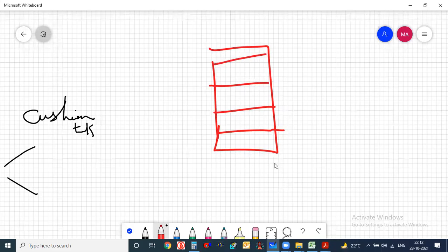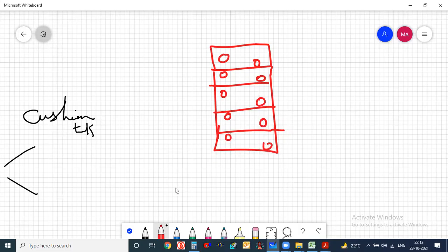Now on every floor, for example, I have two hydrants, one hydrant here and one hydrant somewhere here. So what I will do is connect these two hydrants with the standpipe. One pipe will come and connect directly, then interconnect with this particular hydrant. Same way it will connect here and interconnect with this.